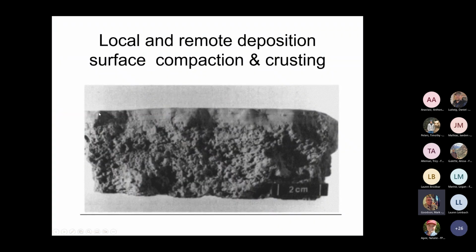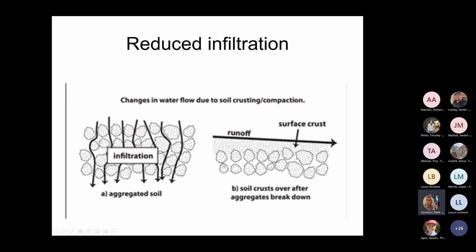When those sediments settle down on the surface of the soil, some of them just sink right down, some of them get into the runoff. The ones that settle down locally and along the slope form a crust on the surface of the soil. This is like an impermeable shingle over the surface, which increases the amount that's running off, because it really damages the infiltration of water into the soil, because we're destroying soil aggregates.